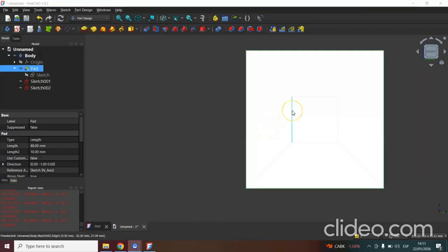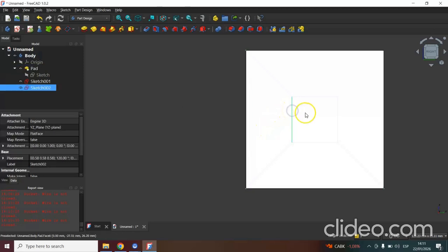So now from here we have to click this line using Control on your keyboard. Keep pressing Control. Click here this line, and finally this line, and click here on Pocket. These yellow buttons are to create the solid parts, and these blue buttons are to create hollow. Okay, hollow shapes, hollows inside the parts. So click here, Pocket,